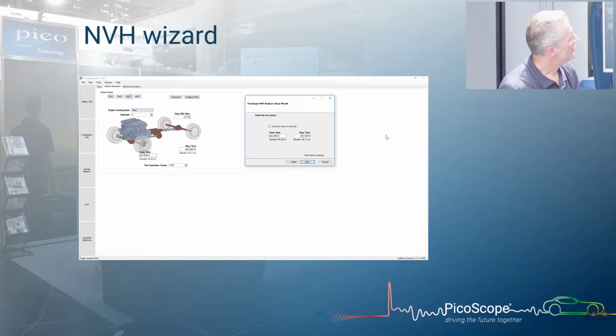Next up then is tyre size, and we've got to be quite strict how we enter tyre sizes. So it must be, in this example, 225/45 capital R 19. If you get that wrong, it will put an exclamation mark and ask you to correct the entry and show you where the entry is incorrect.